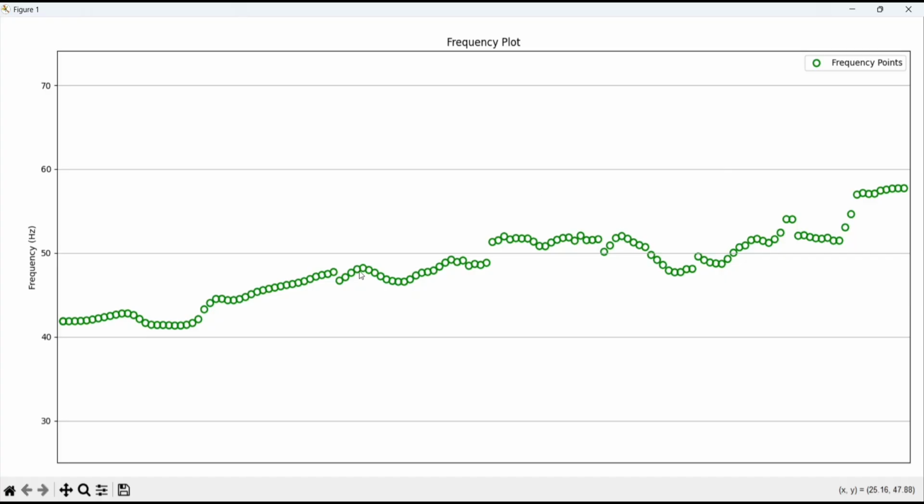Meaning if the frequency dips, then it will support the grid by injecting more power, and if the frequency is higher, meaning power is more than the load demand, then it will absorb the power and produce hydrogen if the hydrogen storage system is connected, and it can be charged if the battery energy storage system is connected.